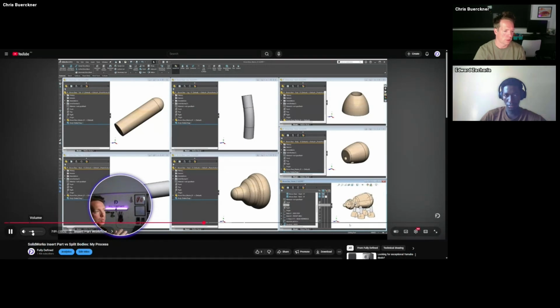We're back. So I've split each file into its own child part. I used a series of save as to save duplicates of each file. And then I changed the delete keep body feature to select a different body. Now I'm ready to create the assembly.